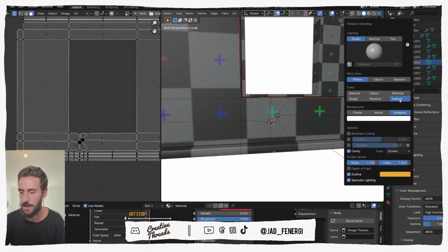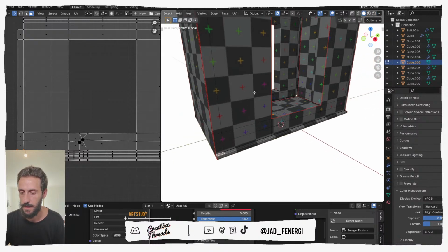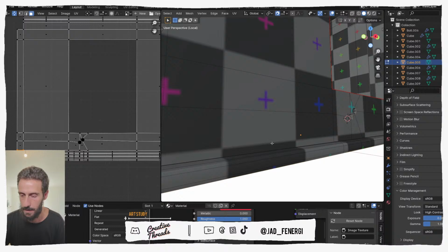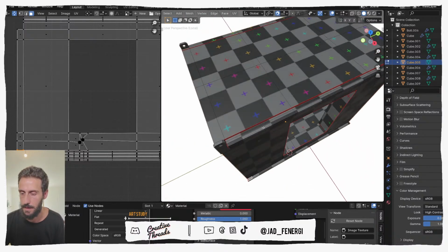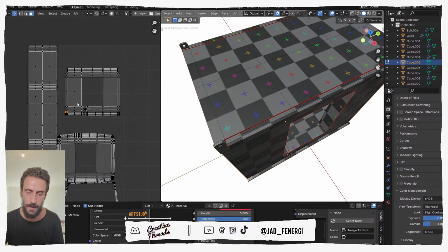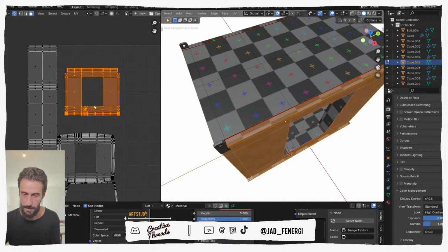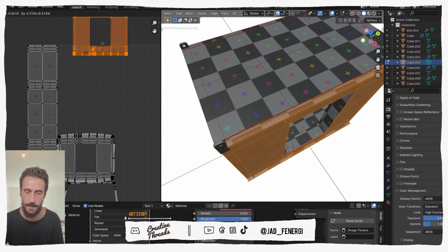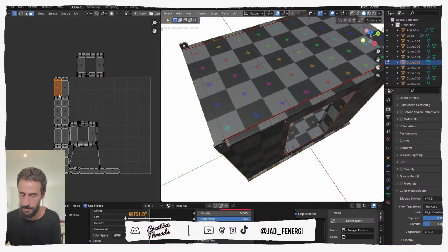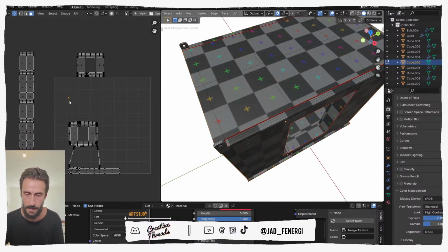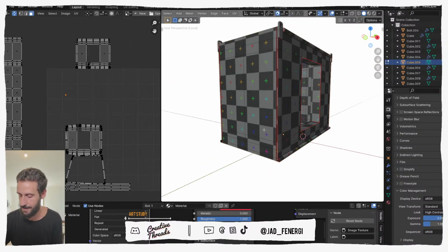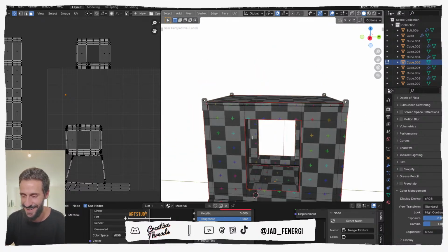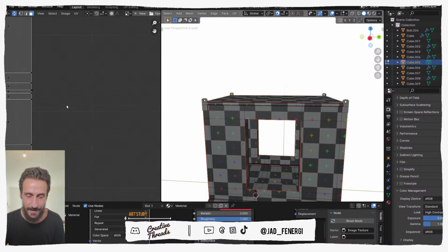But if you check the texture now, you can see that the texture is wrapping properly on all the sides here and here. And you don't have to worry much about packing, because in the end there's a way to pack everything automatically. You can even put them outside if they are bothering you. So press L, move it outside. There's a single vertex in here. This is something that you always want to see. That's fine. Let's make sure.